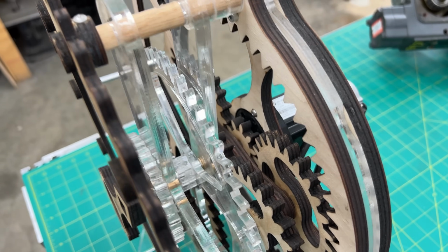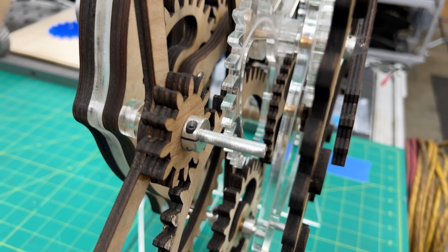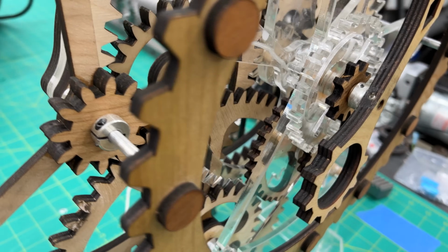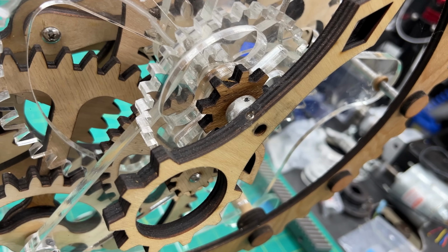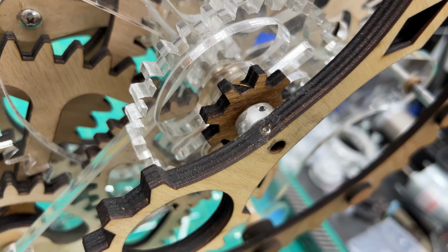So there are many ways to approach this, and I won't cover all of those in this video, but I do want to say it's worth taking the time to think carefully about this joint, especially if you need to transmit a lot of power. Now, in my clock, for example, the forces between the various gears is very low. You really only need enough force to be able to move all of the gears on their respective shafts. So in some cases, I didn't even put a hub on the gear.